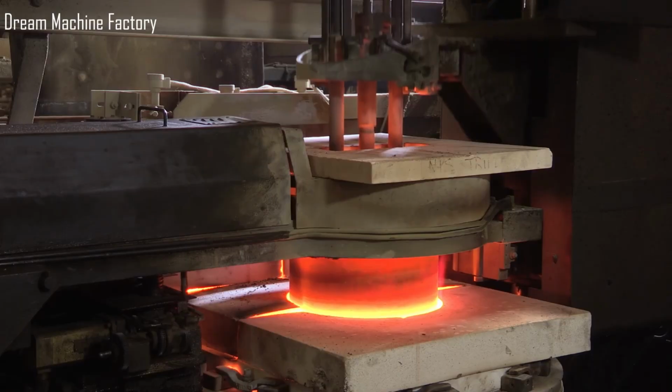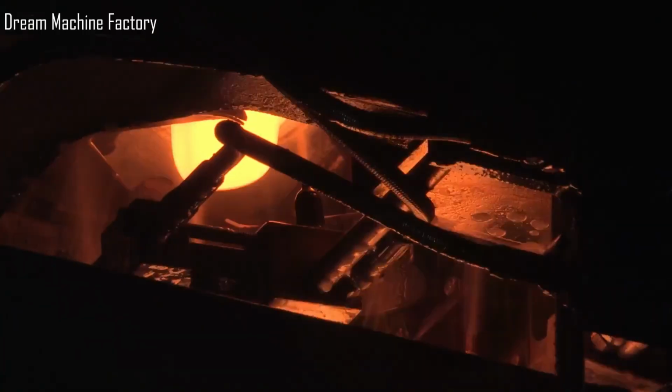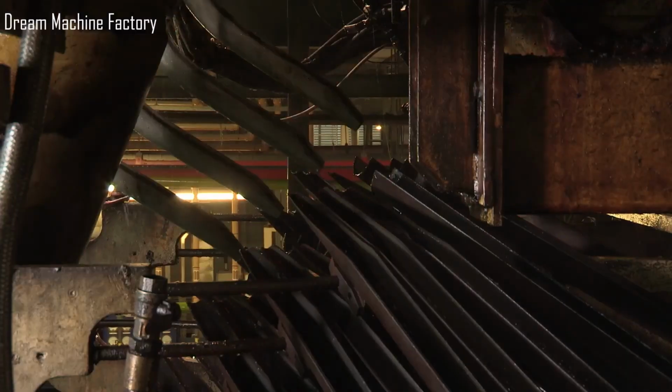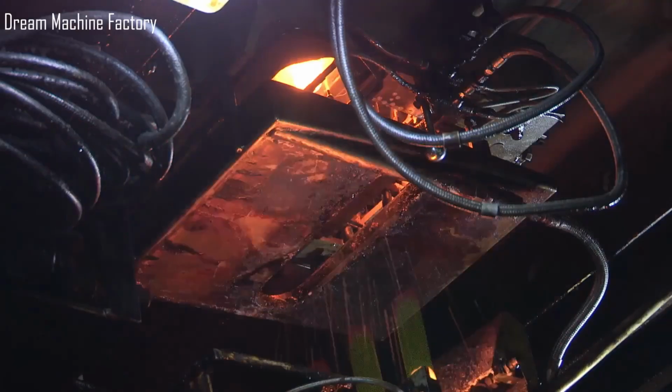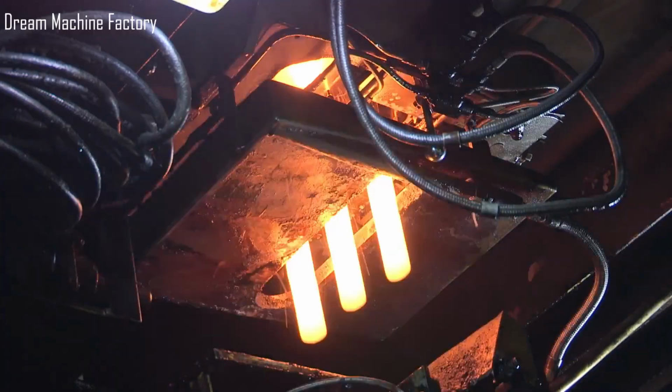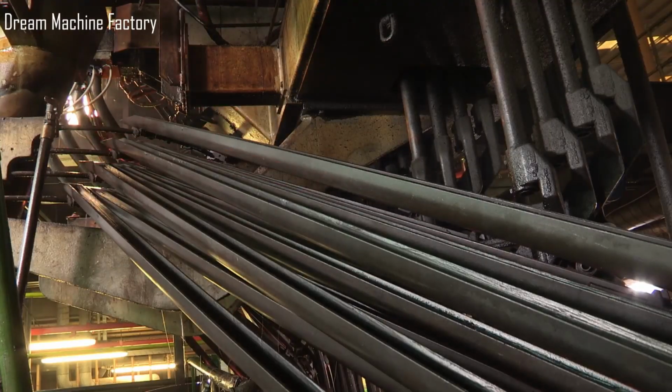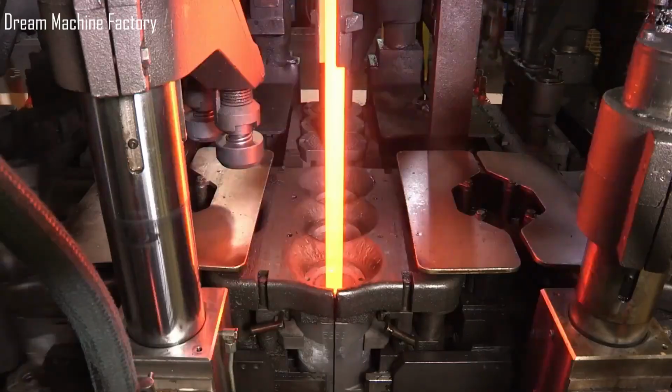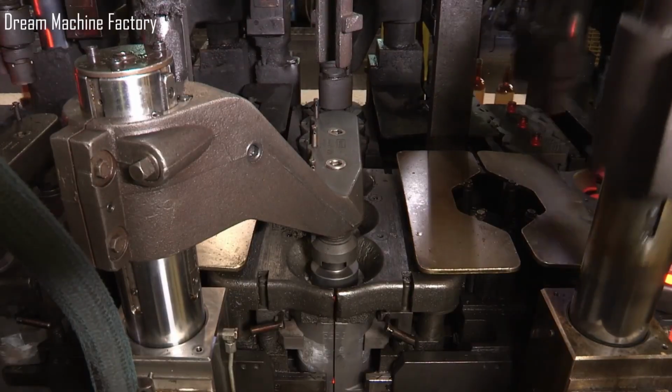This molten glass then flows into a forehearth, where its temperature is carefully stabilized to ensure uniform viscosity. From here, a plunger pushes the glass through an orifice ring, producing continuous streams that are cut by mechanical shears into gobs, precisely measured portions ready for shaping.